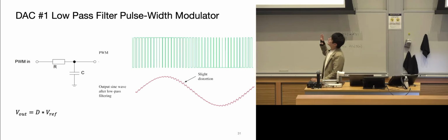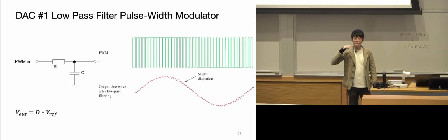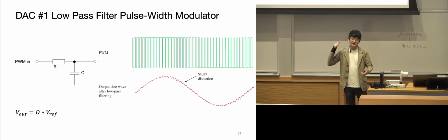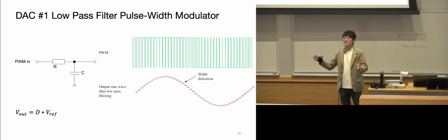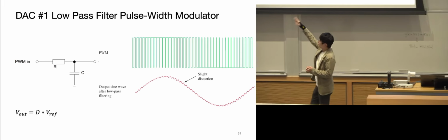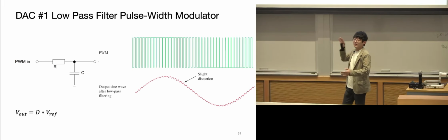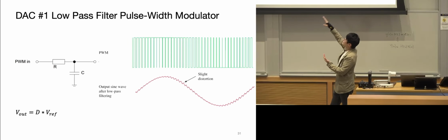Just think of, for a PWM signal, it takes some time for your PWM signal to generate, right? You have the period that needs to be set. You have the duty cycle. That means each of these PWM signals will take a various amount of cycles to generate. And on top of the actual charging time you need for this RC circuit, that's additional time added to it. So you can almost think, this type of